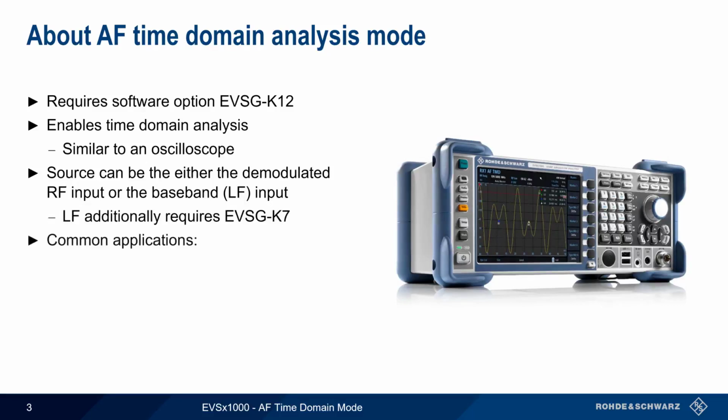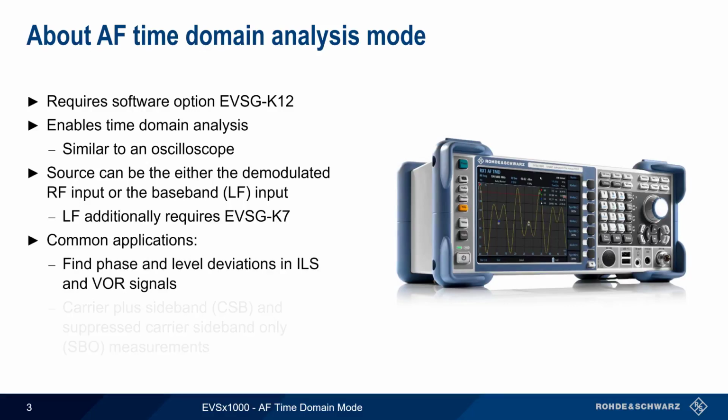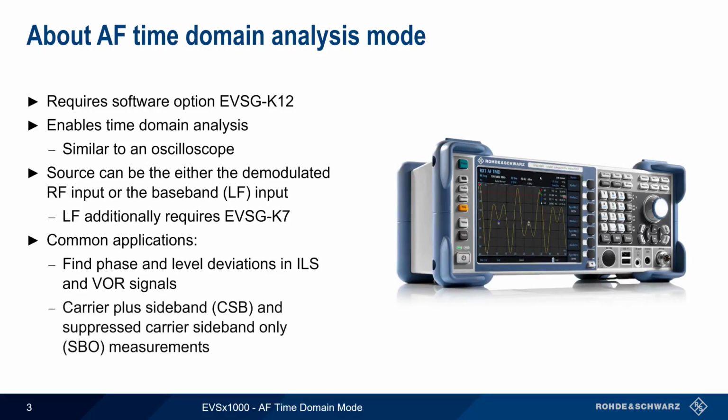Some common applications of AF time domain analysis mode are finding phase and level deviations in ILS and VOR signals, as well as analysis of carrier plus sideband or suppressed carrier sideband only signals.